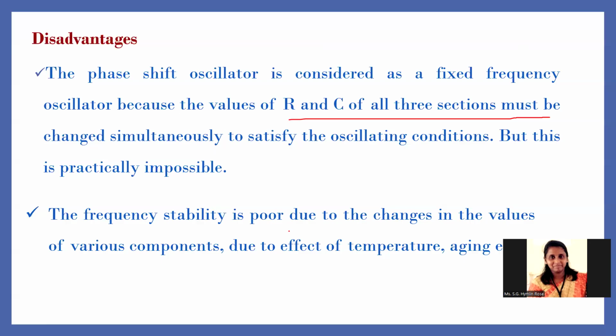So this is about the RC phase shift oscillator. It has two sections in order to satisfy the Barkhausen criteria condition. First, you have a common emitter amplifier with 180-degree phase shift and another three RC sections forming a 180-degree phase shift. Each section will have a 60-degree phase shift. After that, we solved by applying the loop condition equations for all the three loops, and you have obtained the condition for oscillation and the frequency of oscillation. Then the minimum value of HFE also we have obtained.